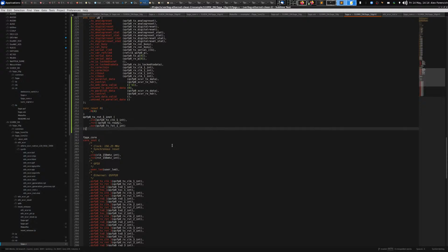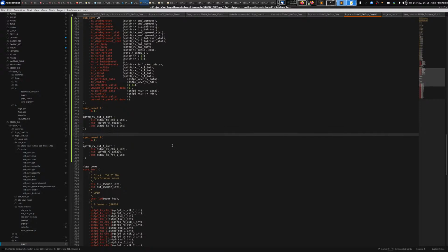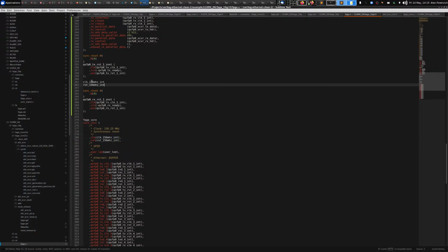Okay, so there is TX reset, and then I copy that, and then this RX, all these TXs. Oops. All right, so all RX, and this one, that one should have been TX. Okay, cool. And then one other thing I need to do is the core needs to run at 156 megahertz. So I'm just going to steal the first transmit clock and use that.